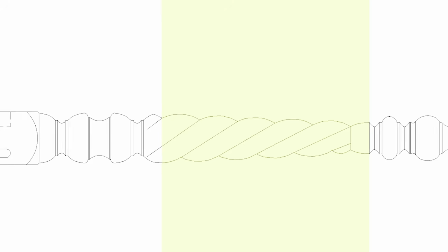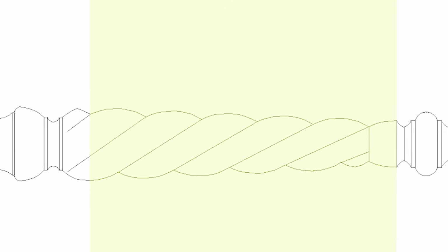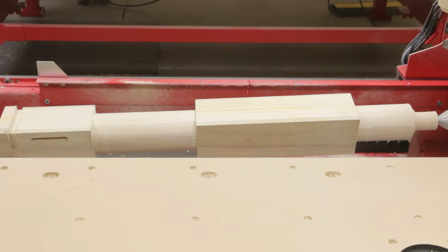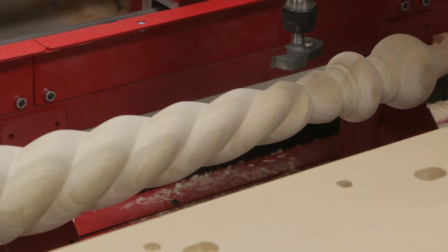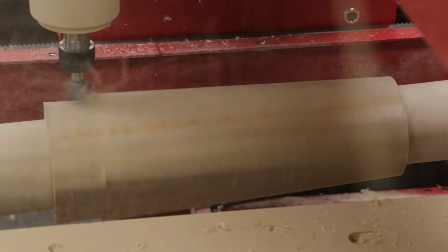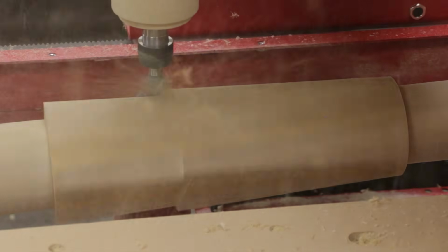Many spindle designs gradually taper straight down to a smaller diameter. Legacy's unique 5th axis feature will tilt the stock, making it possible to match the tapered surface to the face of the cutter. Almost every toolpath in conversational CAM can be applied to a tapered surface.